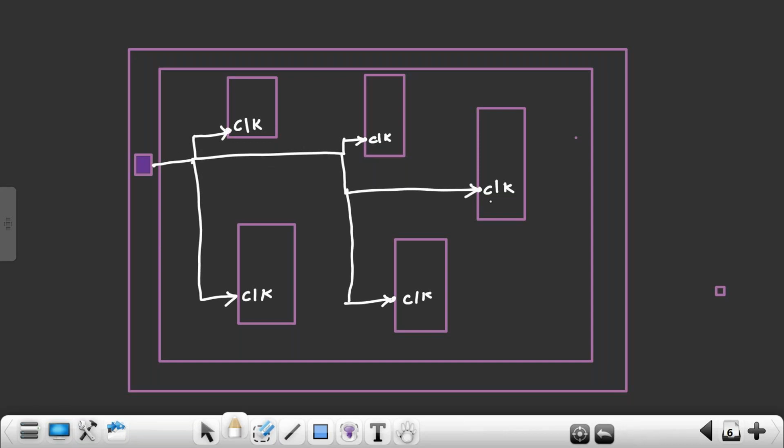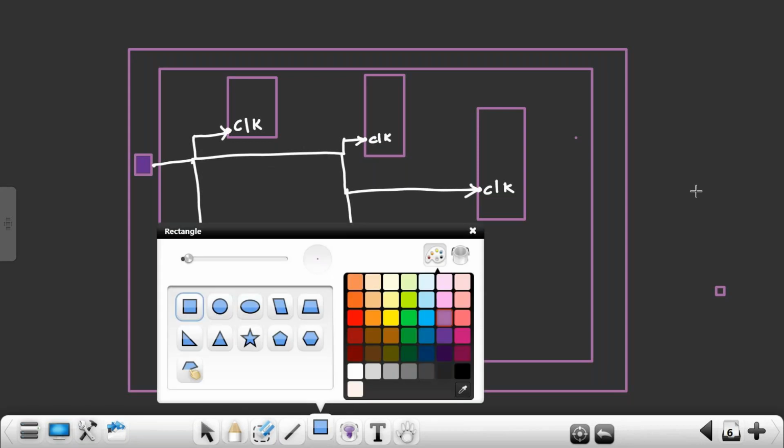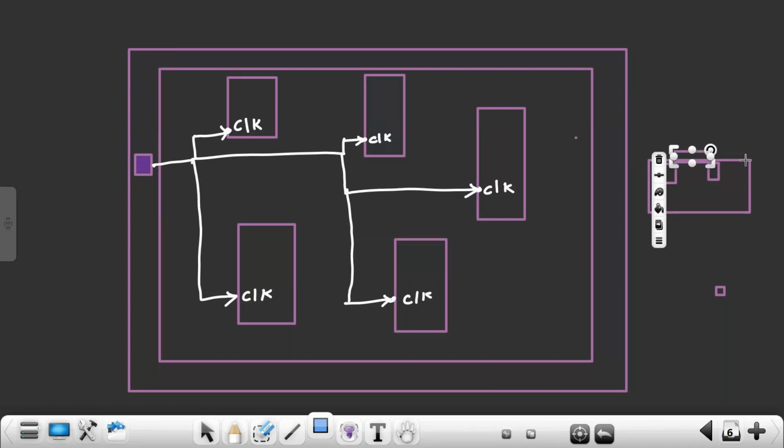Every cell has pin capacitance. If you see the cell, you have source, drain, and after that silicon dioxide. On top of it you have the gate. For an NMOS, you connect a positive voltage to the gate. In between we have silicon dioxide, and in the channel we have electrons. So here it will form a parallel plate capacitor. This capacitance is also found in MOSFETs: gate, silicon dioxide acting as dielectric, and the negatively charged channel. It will form a parallel plate capacitor. Those capacitances are called pin capacitance.